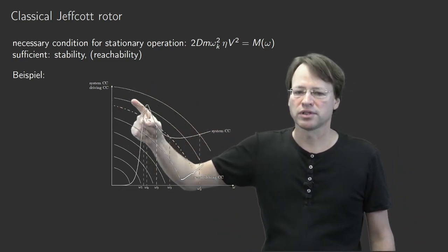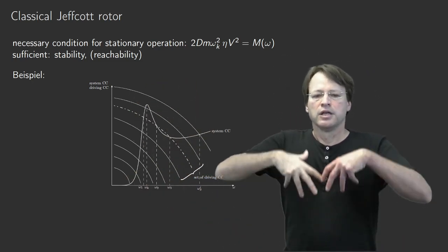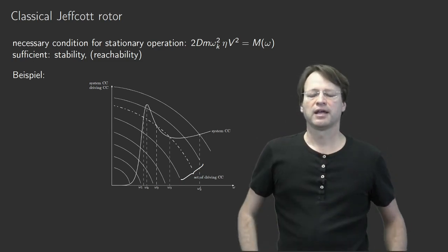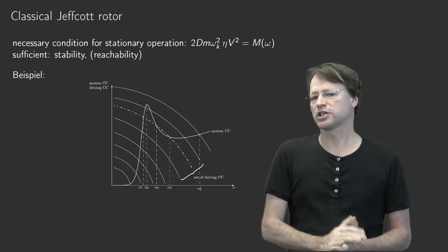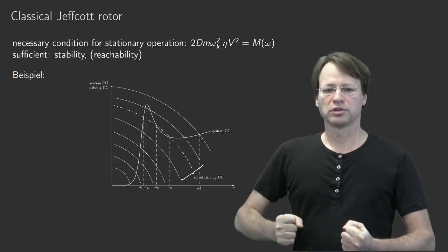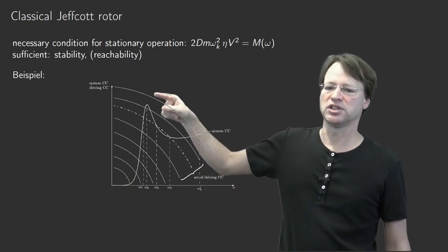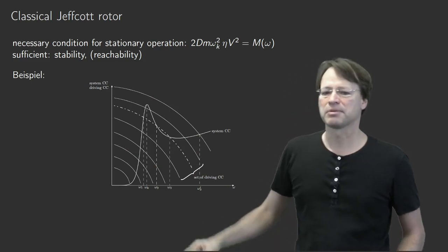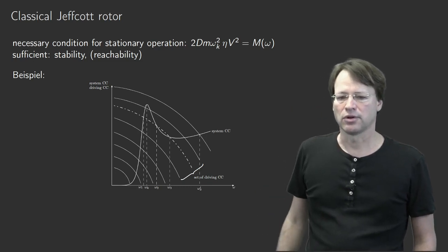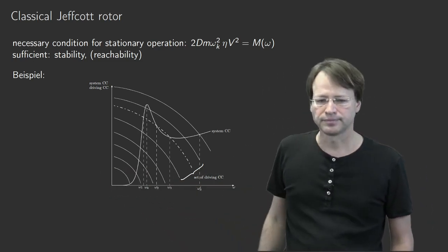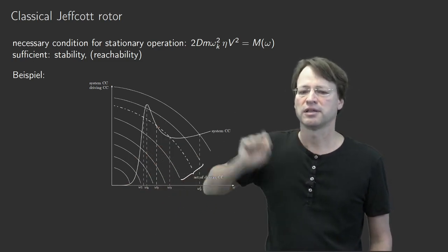As the driving torque is now much larger than the system characteristic torque, you create a very huge angular acceleration, and as a result of that large angular acceleration, your rotor starts to increase its rotational velocity from 0 going up. And you see that translates into going up that system characteristic curve. So on that omega line for the rotational speed, we move to the right and your system characteristic curve increases until you reach that balance point.